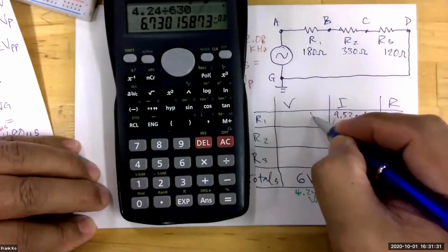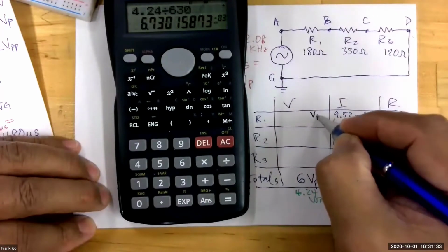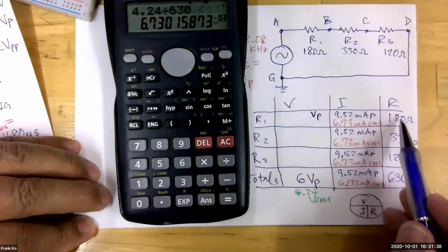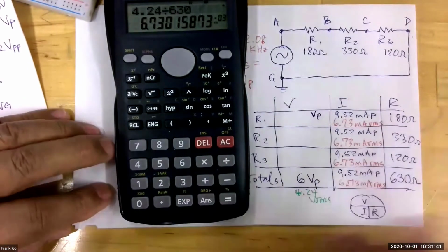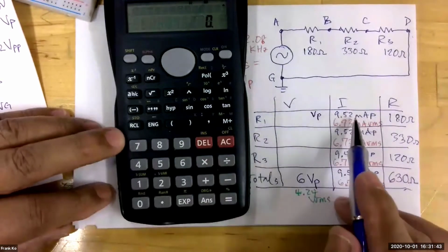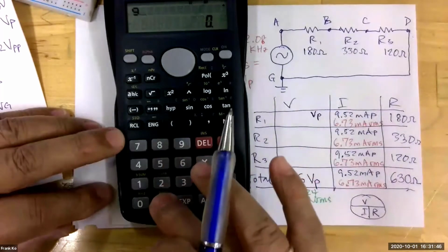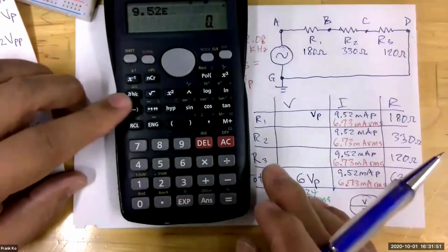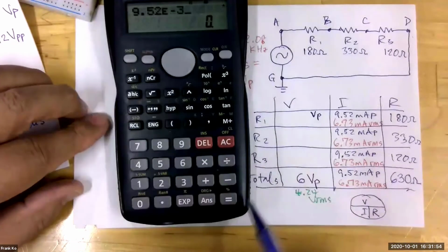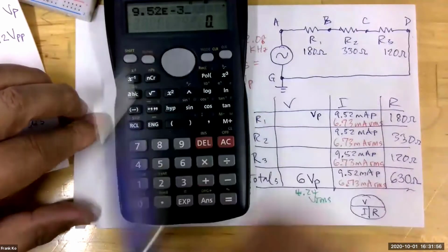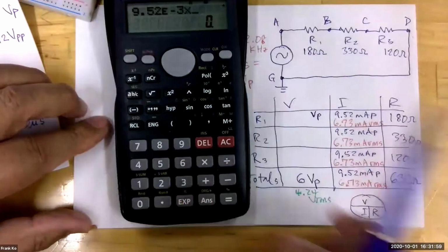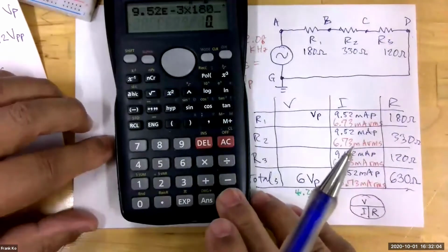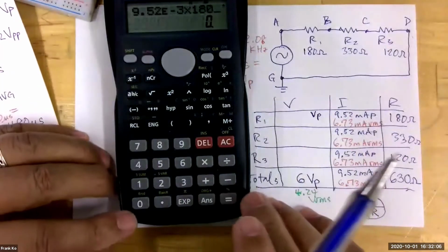So in order to calculate my volts peak across R1, I would multiply my peak current times my ohms, yes? So everybody, let's go ahead and do that calculation. Let's take 9.52 milliamps. How do I key in milli? Exponent -3. Is that what I have? 9.52 milli. And now I'm going to multiply that by 180. And the calculated result on this, Robert, works out to be what value do you calculate, my friend?